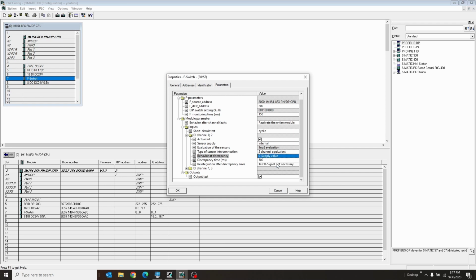This does get changed. I always change this to supply a 0 value, not just the last value known, because if something goes wrong, we want to kill the system. Therefore, it should say 0. No good. Do not go.